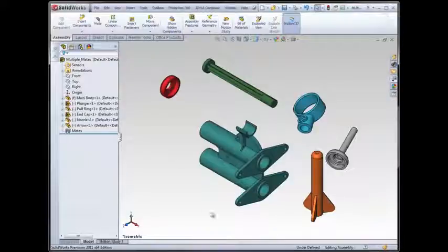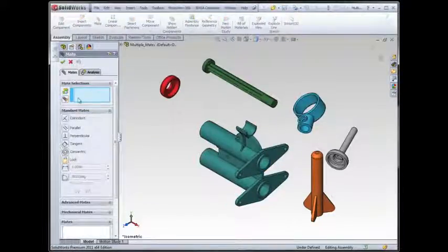In the case of this assembly, lots and lots of components, five of them to be specific, are all going to be related to this cylindrical face. I'm going to have a concentric mate to that face. Rather than selecting this face and this one, green check, this face and this one, green check, etc., within my mate property manager I have an option called multiple mate mode.